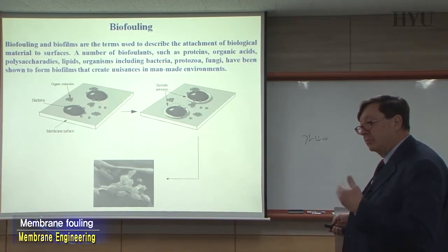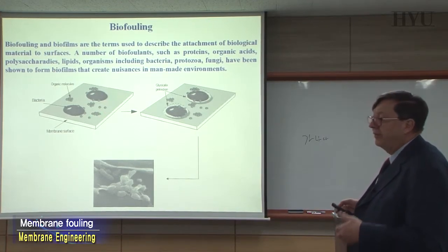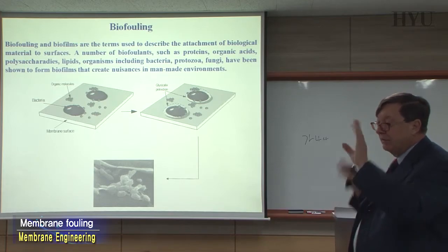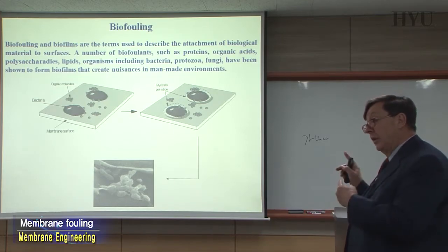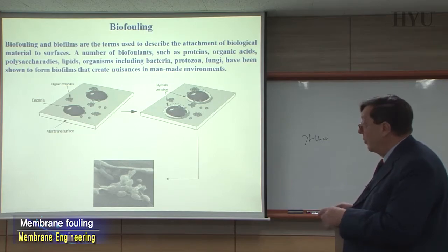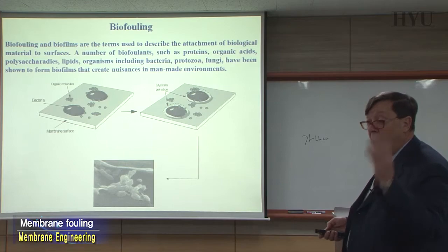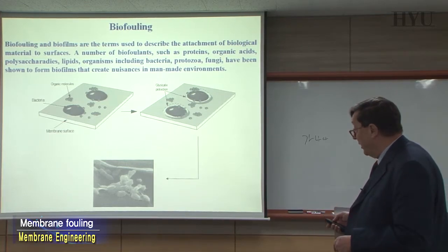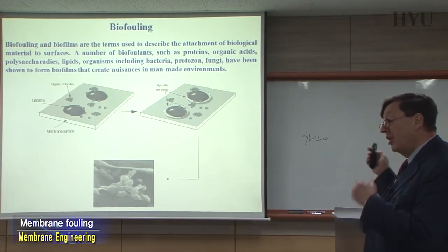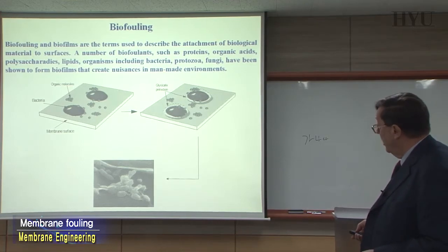These things take time. So you realize at one point that everything was okay, you have very slow decay, not very significant, but when it starts to be significant, when the film is formed, it's too late to clean the membranes, and you lose all your system. And that can be very severe. You have to stop the plant and sometimes change 100% of your membrane.